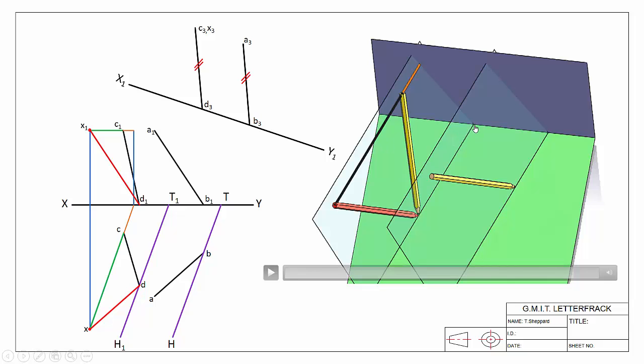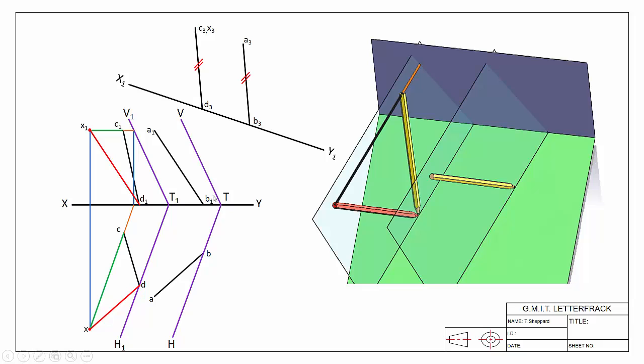I have a second point here where my horizontal trace hits the back wall, so that's my vertical trace there. And because our vertical trace for our second plane is parallel to it, well, we just say, well, there's my point. I go parallel, and now I found my vertical trace. So that's how we locate, first of all, our view where we see the two skew lines as parallel, and how we locate the traces of our two parallel planes. So there's just the two planes filled in.